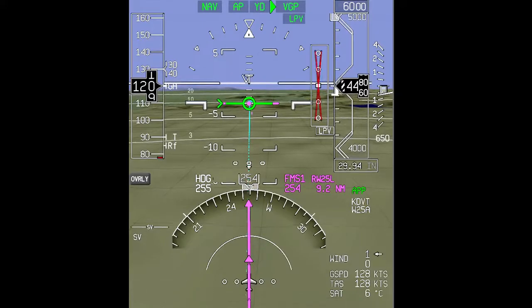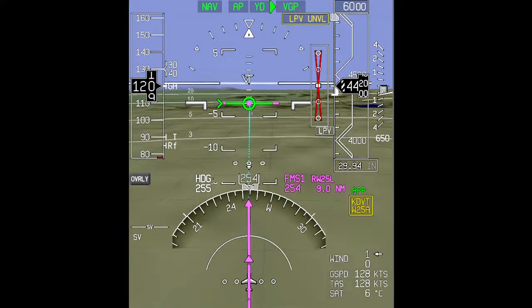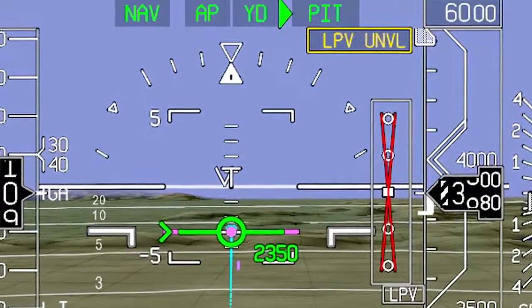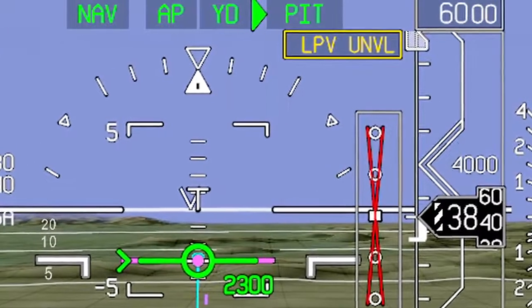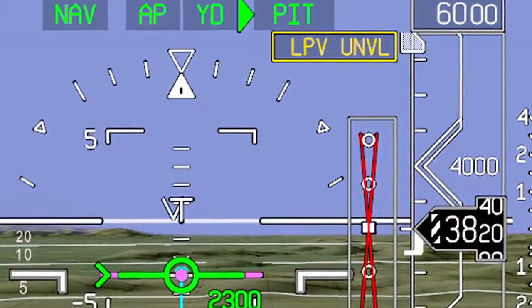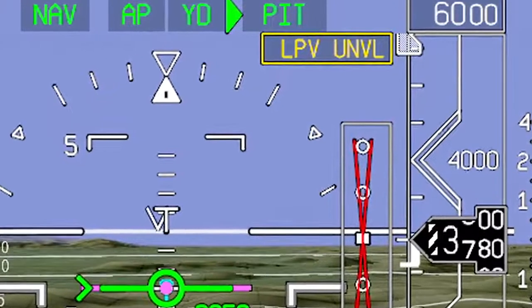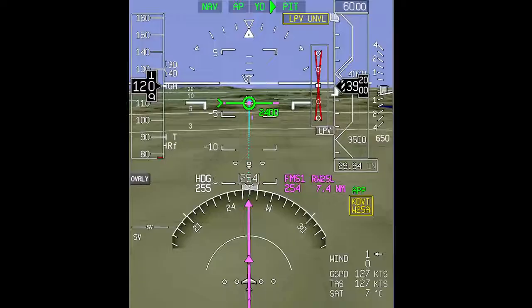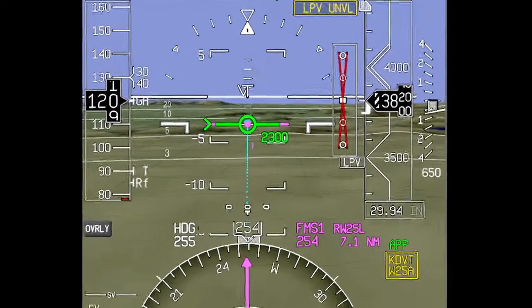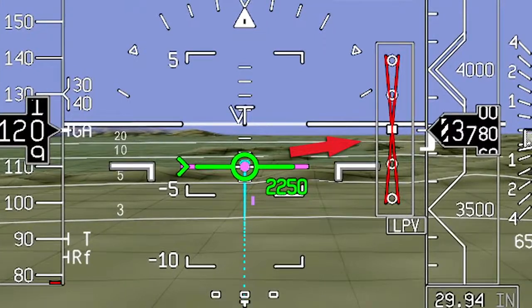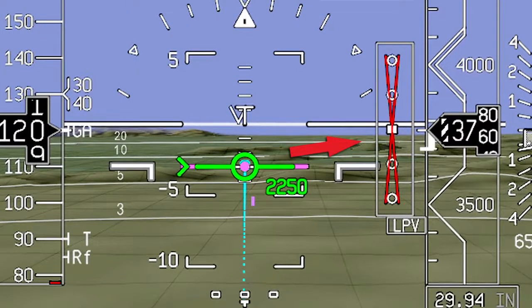Pilots must be familiar with the fail-down capabilities of their SBAS system. An amber LPV annunciator is displayed on the PFD up to 30 nautical miles from the landing threshold when conditions exist that would prohibit descending to LPV minimums. In addition, if the amber LPV annunciator is displayed or continues to be displayed inside 2 nautical miles of the final approach fix, a red X is displayed on the vertical deviation indicator.